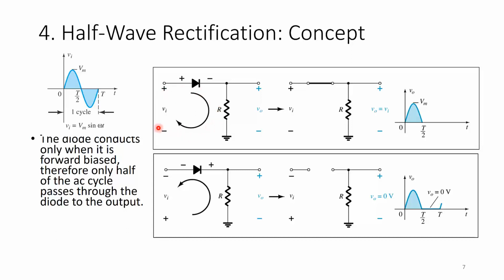So this would make this diode forward biased, and therefore it will switch on. But if it is in the negative cycle, so Vin, when it is going through the negative cycle, it would then flow in the opposite direction, because it's negative. And this would make the diode reverse biased. So when it's in reverse bias, it is essentially an open circuit.